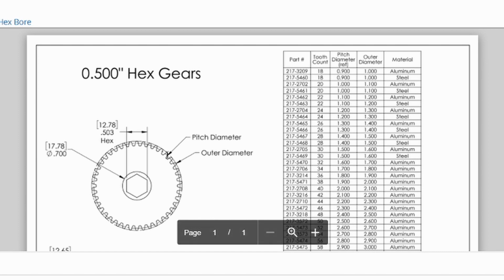If I were to explain this better, let's say we CADed a circle that has the diameter of the pitch diameter, and say we wanted to mesh two gears in real life. We would CAD it so that there would be two circles that have the diameter of the pitch diameter, and those two circles would be tangent.